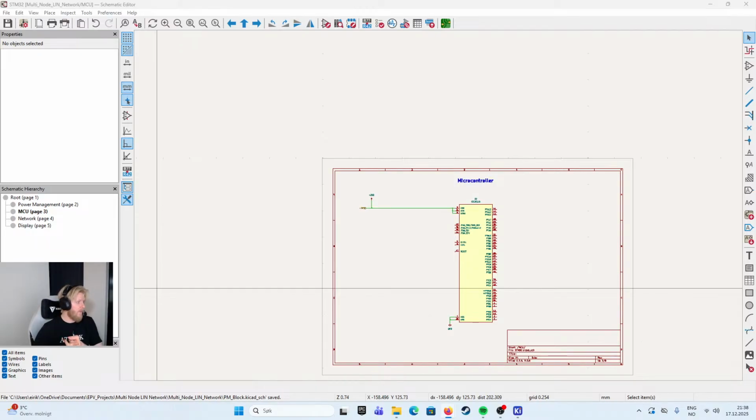For improved performance, it is recommended to use 10 microfarads, 0.1 microfarad, and 1 nanofarad capacitors in parallel. All coupling capacitors should be placed as close as possible to the corresponding supplier ground pins. Contact your local field applications engineer for best analog routing practices.